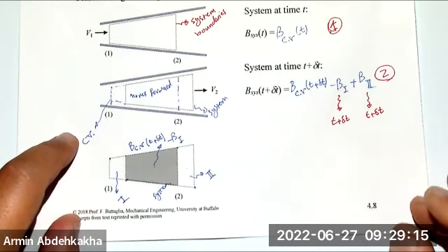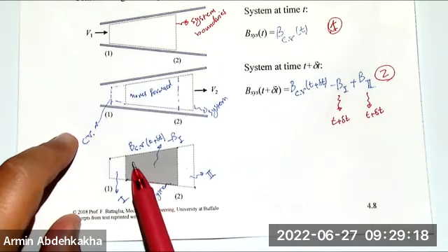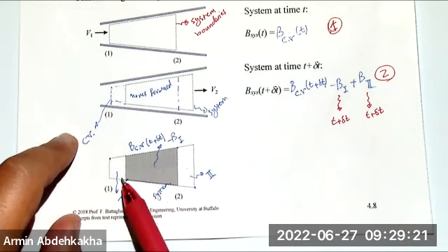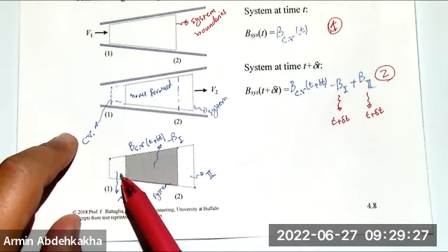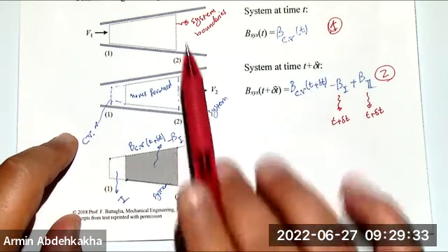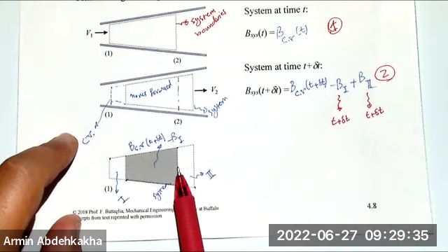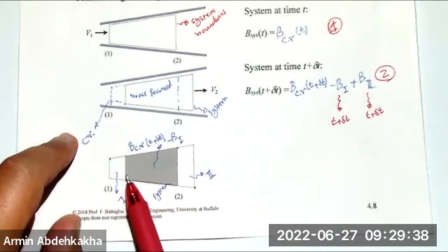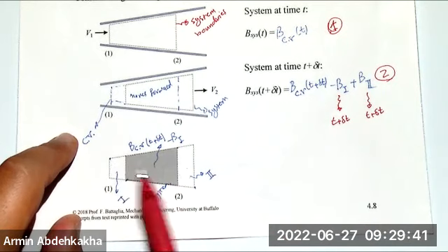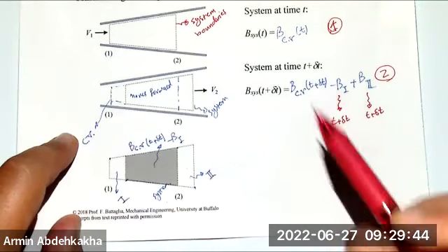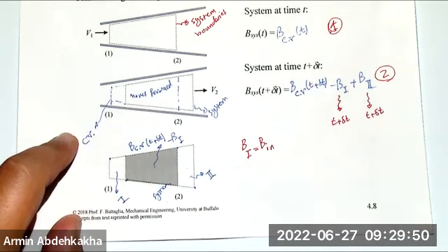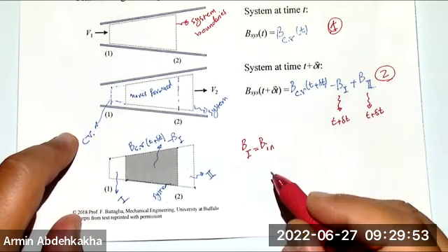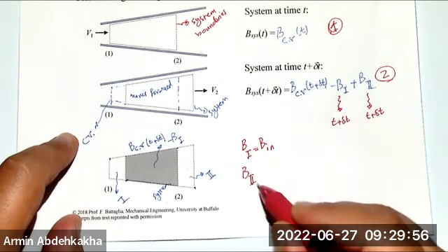In the control volume, which was from here to here, B1 also can be seen as the amount of fluid that comes inside of that. Let's say that this is your control volume like this, okay? Your control volume, which is fixed. Then the flow moves. This part of fluid particles are coming in and these are going out. So that's why we can say that B1 is your B in, again at time t plus delta t, and B2 is your B out.